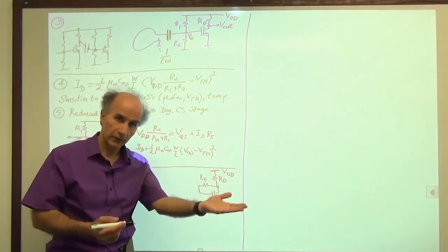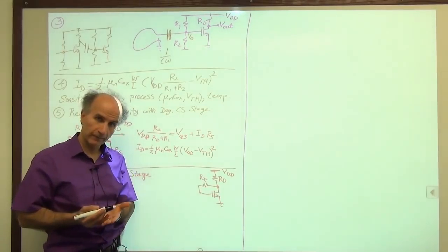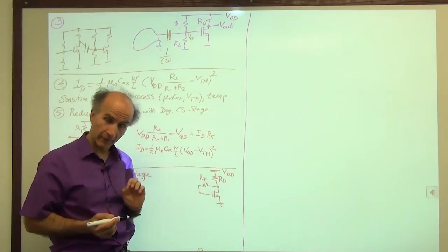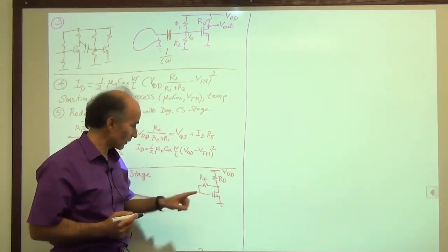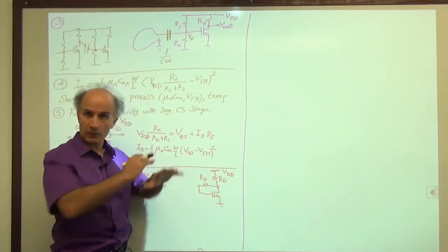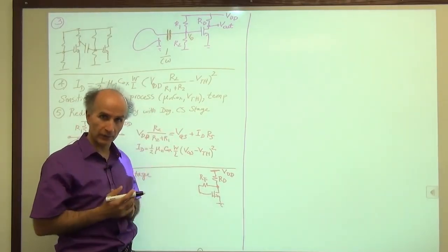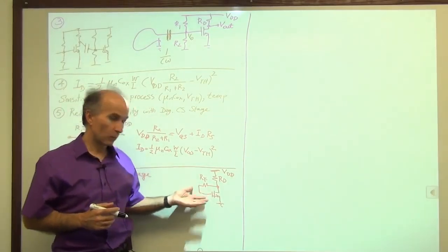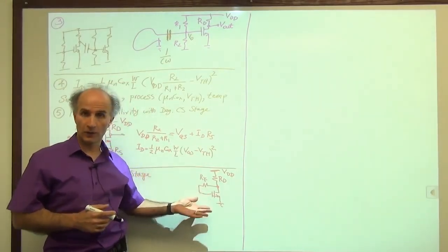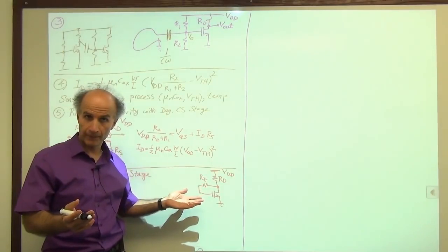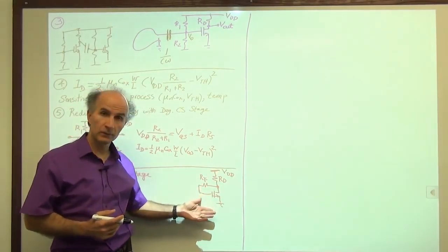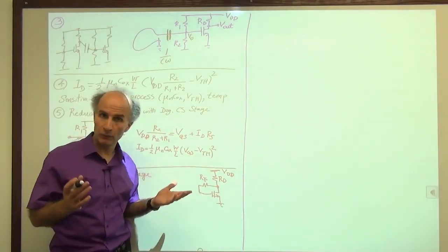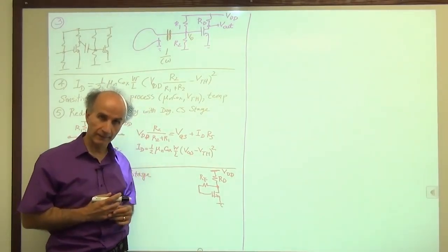We try one wafer today, we try another wafer tomorrow. And the only thing that changes from one wafer to another is the threshold voltage of this device. Let's suppose everything else is constant. So on wafer number 1, the threshold voltage was 0.5 volts. But when we went to wafer number 2, the threshold voltage became smaller, 0.45 maybe, 50 millivolts less.